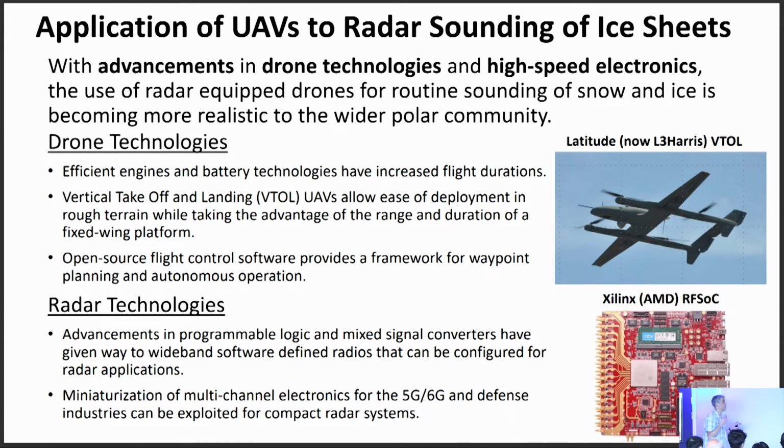And also radar technologies. We've seen an explosion of software-defined radios, and also miniaturization of multi-channel electronics, both for 5G and 6G, as well as the defense industry. What we see over there on the right is a number of these vertical takeoff and landing drones, which provides us an opportunity to deploy these in remote locations. And on the bottom there are new electronic devices, and we have a Xilinx RF SoC, which within a single chip has a 16-channel transmitter and a 16-channel receiver, synchronous, with multiple gigasample, gigahertz capabilities. This is something that 10 years ago we would have had in a big rack in the P3 to have these capabilities.